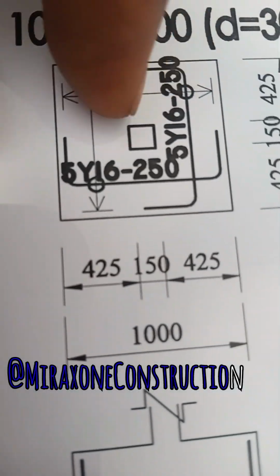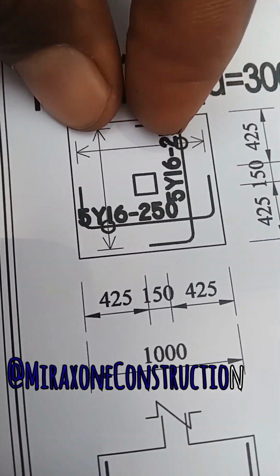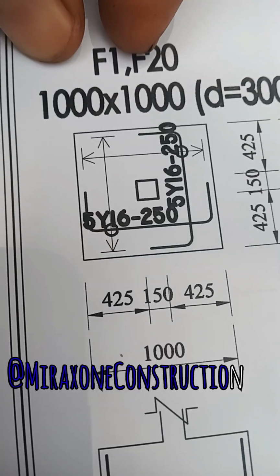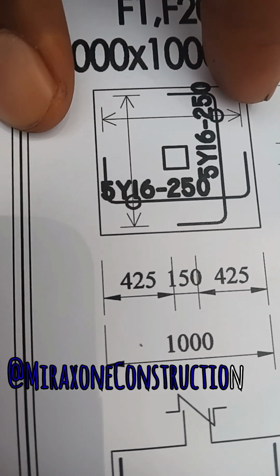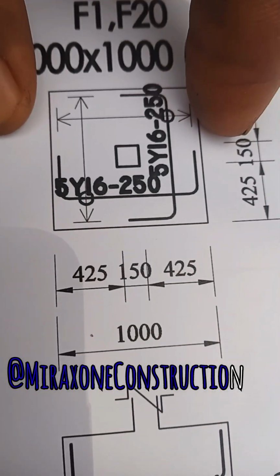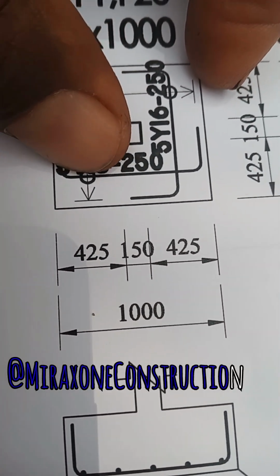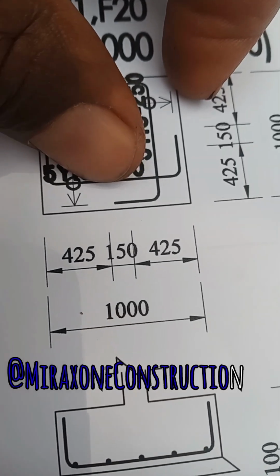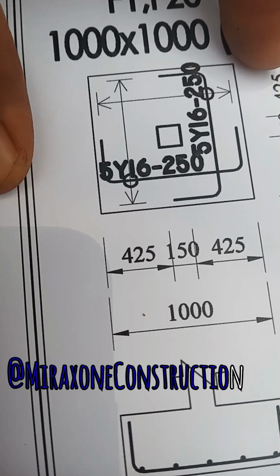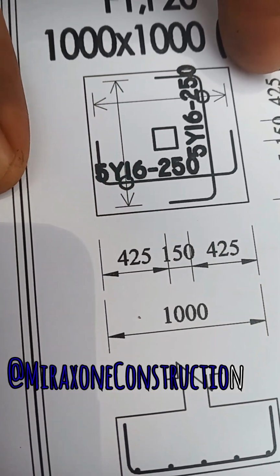So let's get into the structural detailings of this type of reinforcement. As you can see here, it reads 5Y16 dash 250. Yes, I'm reading what I'm seeing here. Let me explain. 5 stands for 5 pieces. You are going to cut it in 5 pieces.